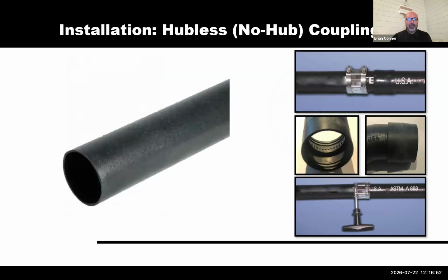Now, let's talk just a little bit about the joining method for cast iron. Again, in the Canadian market, your MJ or hubless pipe and fitting system is the predominant system. Manufacturers in the U.S., Charlotte, Tyler Pipe, and ABNI, all manufacture hub and spigot and even extra heavy cast iron pipe. But I've been told that unless it's a historic project, hub and spigot is not typically used in the Canadian market, that it's almost exclusively MJ. So we're going to focus solely on that today.